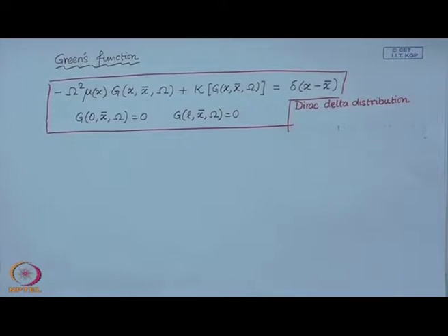Which means that Green's function is the solution of a one dimensional continuous system, what we are discussing at present, when you apply a harmonic concentrated forcing of frequency capital omega applied at the location x equal to x bar. So, the solution of that system is the Green's function.